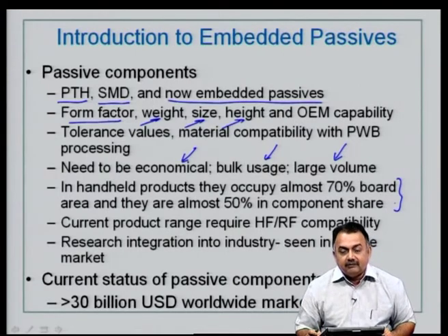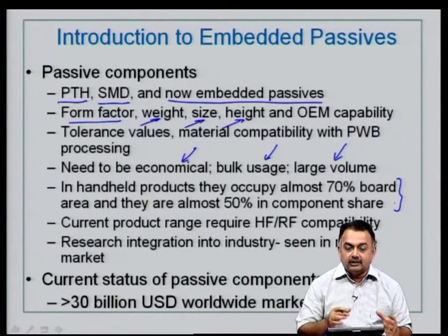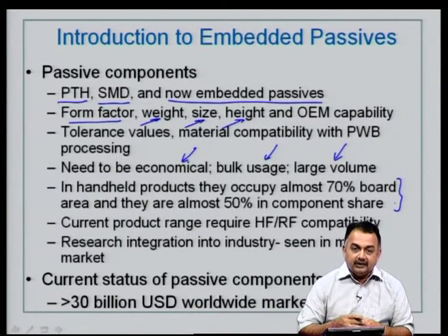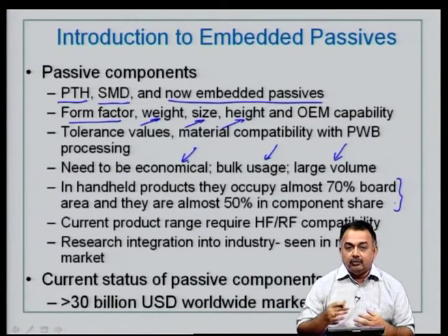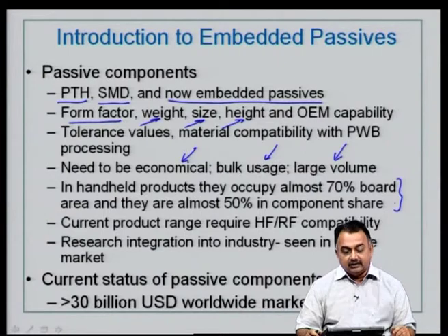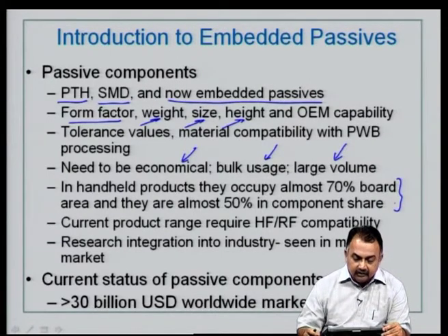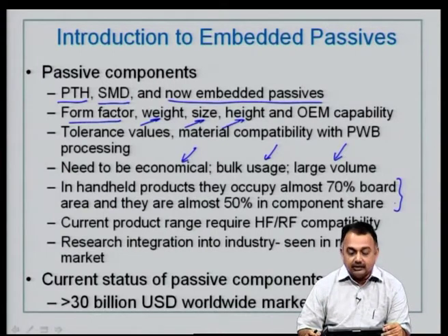And in the case of passive components also, because as you have seen, the footprint area of the active devices are shrinking, and it is but natural that you will move into using passive components with smaller footprint area. A large change has occurred due to SMD footprint being very small. And now we are going to see how embedded passives can help in such a design issue.